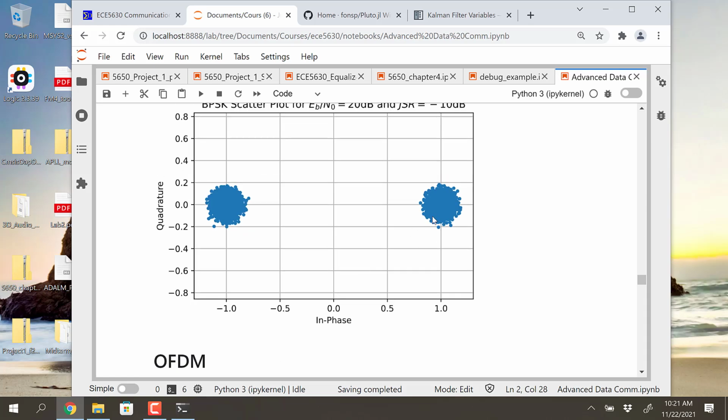If I make the signal to noise ratio really large, the fuzziness on those scatter points will go away and it will become very tight looking, and that is just the interference, because it's synchronous, so it doesn't really have a random behavior. It looks more deterministic in terms of what the interference is doing at this point, just for this scenario. But the diameter doesn't really change. The noise has made it a little bit bigger, but it's the jamming that has made it look like that.